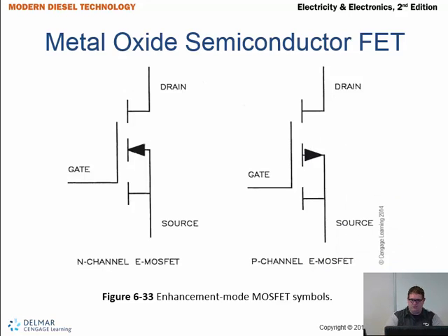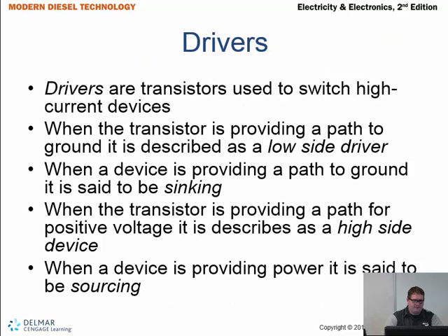That's above technician level. You probably are not going to see that often. All right. Drivers. Drivers are transistors used to switch high current devices. So we kind of talked about this before. When the transistor is providing a path to ground, it is described as a low side driver. When a transistor is a device providing a path to ground, it is also said to be sinking. Okay, sinking, drawing it down to ground.